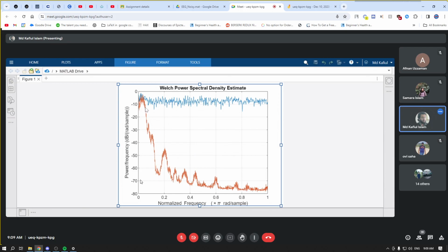Okay. So you tell me what is supposed to be the cutoff frequency of the low pass filter if I want to figure it out from here. What is supposed to be the cutoff frequency? So I need this part, right? Basically, and you see that this part are basically very low in power, so they are actually kind of noise. Okay. So what's supposed to be the approximate one? Okay, 0.1 pi. So that means, can we say that our omega c is 0.1 pi?